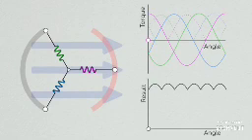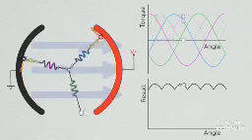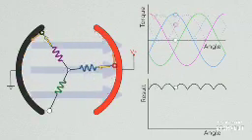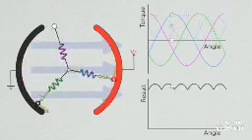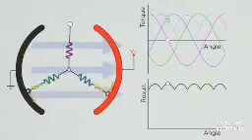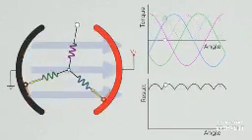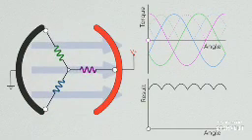So we can actually achieve this torque configuration through some clever mechanical design. By having 2 brushes, one connected to power and one connected to ground, which only contact our loops when they are in these regions, we can have the turning of the motor take care of the switching of our electrical pathway. On a side note, in practice, the brushes are actually a small conductor which contacts a large conductive strip wired to each of the nodes. But I personally find that it's easier to conceptually understand brushed commutation depicted as a point on the node contacting a brushed surface. So now we know how to make our motor rotate from any arbitrary position.